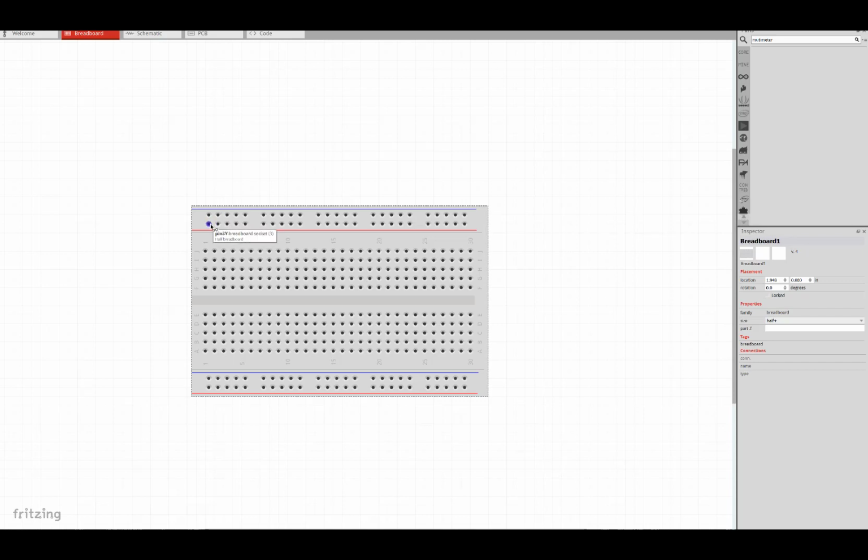So let's say, for example, with a 9-volt battery, the positive terminal connected with a red wire might connect over here, and now we'll be able to tap into any of these holes to get a 9-volt connection. Similarly, the black wire of the 9-volt battery, the COM wire or the ground wire, whatever you may want to call it, would go here, and they'll all be connected and at ground voltage. We'll pretty soon see how we can make those kinds of connections.